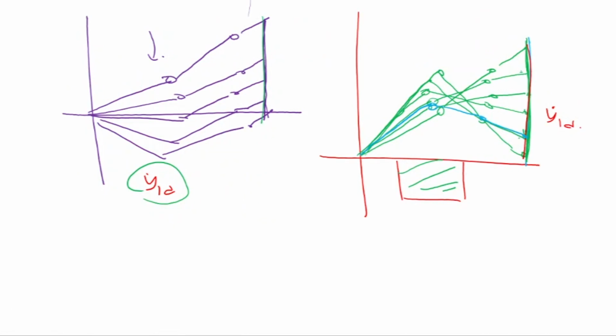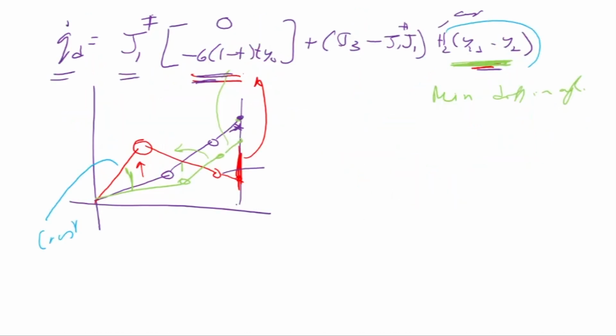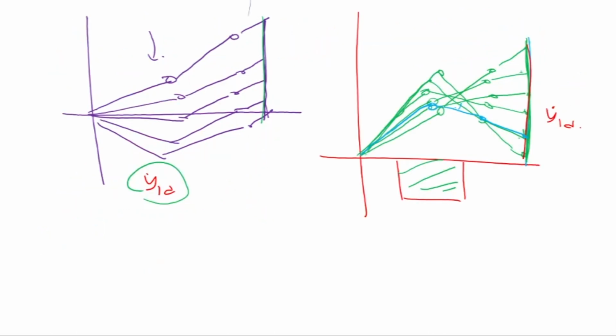So it will start choosing solutions which are near to this solution now. And how is it doing that? It is simply doing that by looking at the angle difference. What it is doing is trying to minimize that, and the result of which is giving you this solution now. So this is an example of redundancy resolution using case 1 and case 2, where we are giving it a subtask and it is following the subtask.